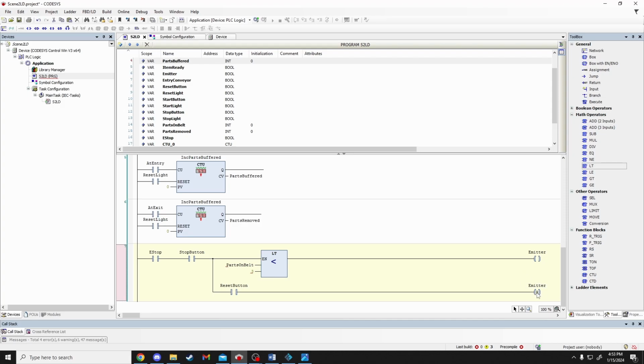So what the set and reset coils do are, if you get even just a short pulse, it will set the coil to whichever state. Set is on, reset is off. It will set it to that state until it receives new information about its state. So you can press the reset button for a second, and it'll hold it off for as long as it